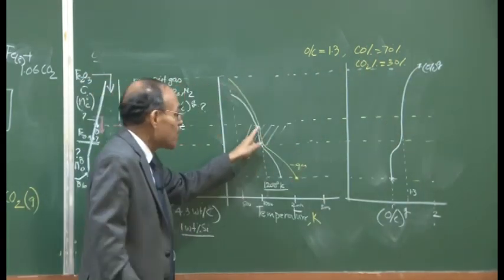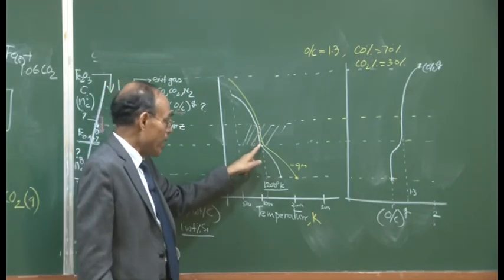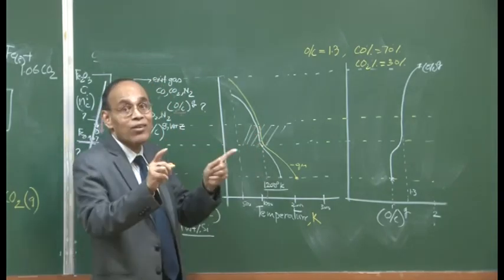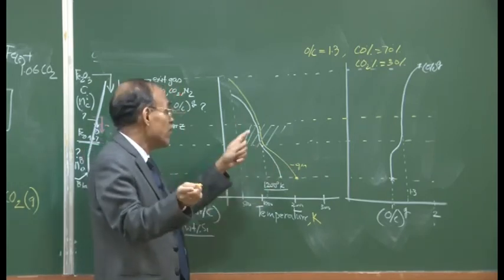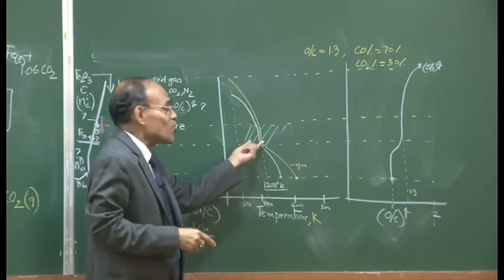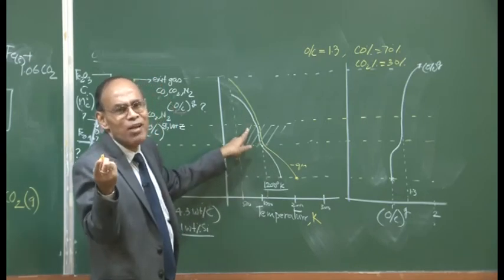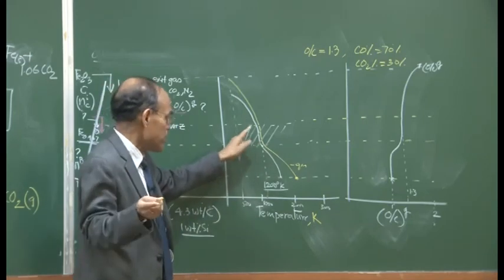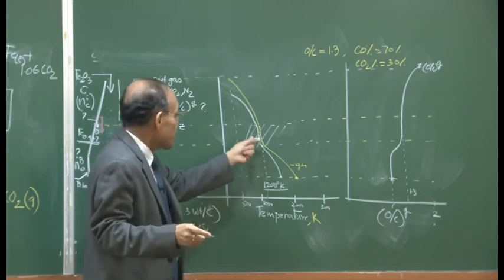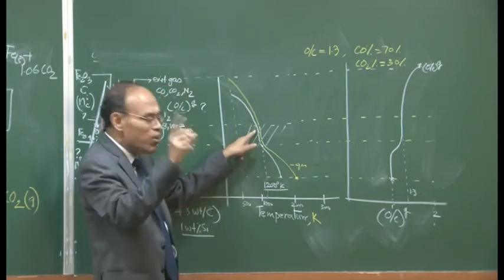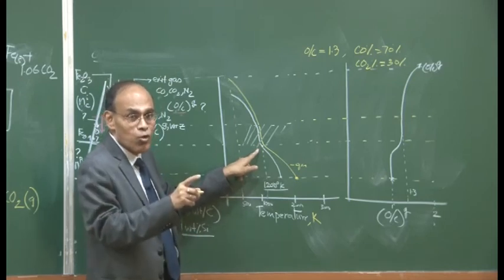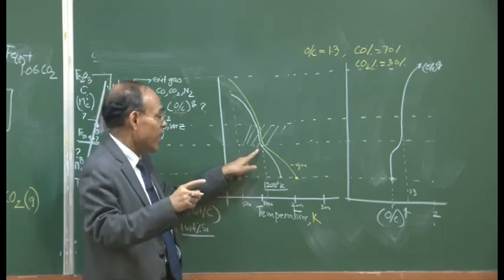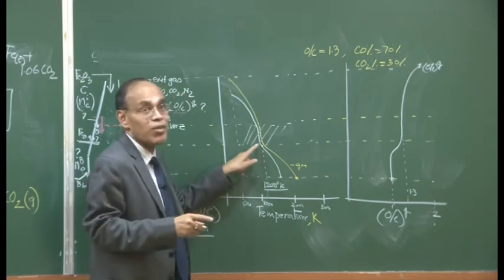So, there is a thermal equilibrium between wustite, which is the solid descending because no other oxides are there, and because coke is descending as coke itself, it is not taking part in any reaction here except perhaps for the gasification reaction. As far as the principal reduction reaction of the iron bearing material is concerned, it is wustite which is getting reduced here with carbon monoxide producing iron and carbon dioxide, and the temperature remains constant.